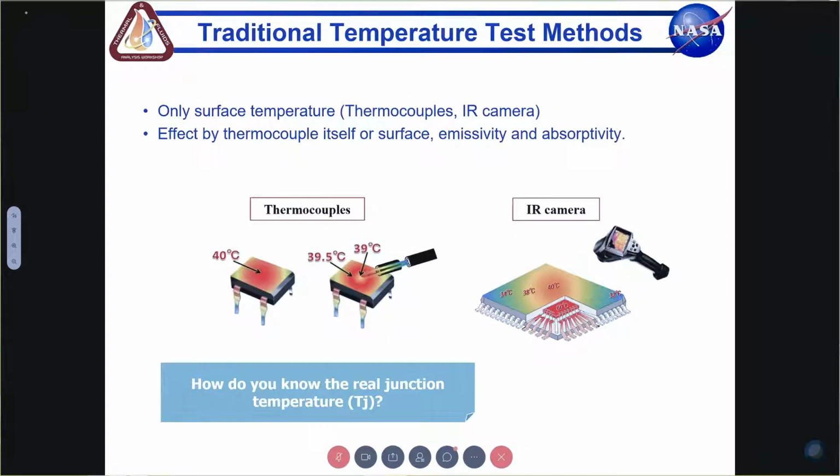If you can't keep an IC cool enough, it may either fail, or you may need to do what's called frequency throttling. You need to go down with the clock frequencies, making the system less efficient. And I've already talked about system margins, for example, system costs, and most importantly, weight has to be reduced.